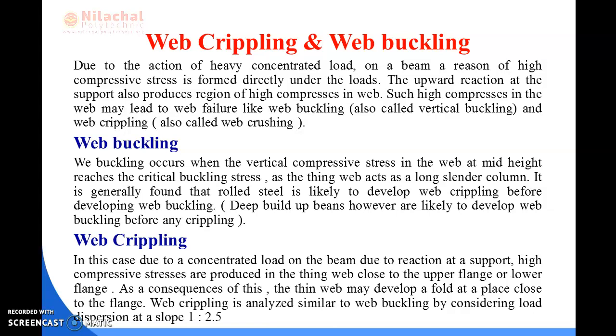First of all, due to the action of heavy concentrated loads, that is point loads, on a beam, a region of high compressive stress is formed directly under the loads. The upward reaction at the support also produces a region of high compressive stress in the web.